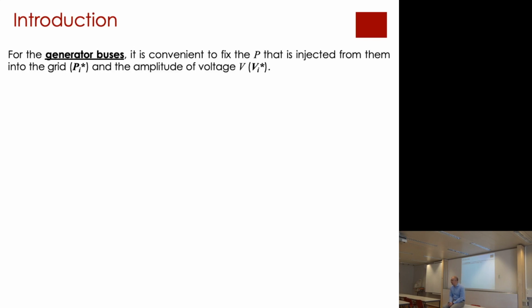When you are solving this nonlinear problem, you are getting one of the possible solutions. It's a problem that has multiple solutions in general, okay? Now, out of these many solutions that you have, you want to pick those solutions that have a technical sense, namely, they represent a feasible state of the system. The voltages of the system should be kept as much as possible close to the rated value. Okay? They cannot change. They should not change. This is due to various operational aspects related to the insulation of the system.